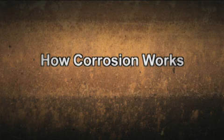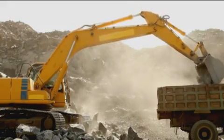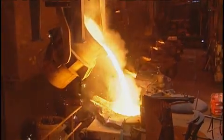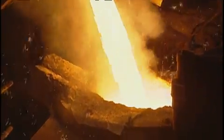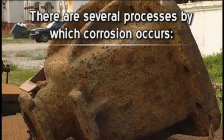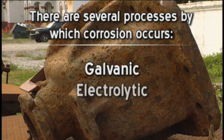To learn how to control corrosion, it's important to understand how the process works. When metals are mined, they are generally found as oxides. By adding energy in the refining process, metals become more useful for manufacturing, but also more reactive. Corrosion is simply the process of refined metal reverting back to its stable oxidized state. There are several processes by which corrosion occurs. Two types most relevant to water utilities are galvanic and electrolytic corrosion.